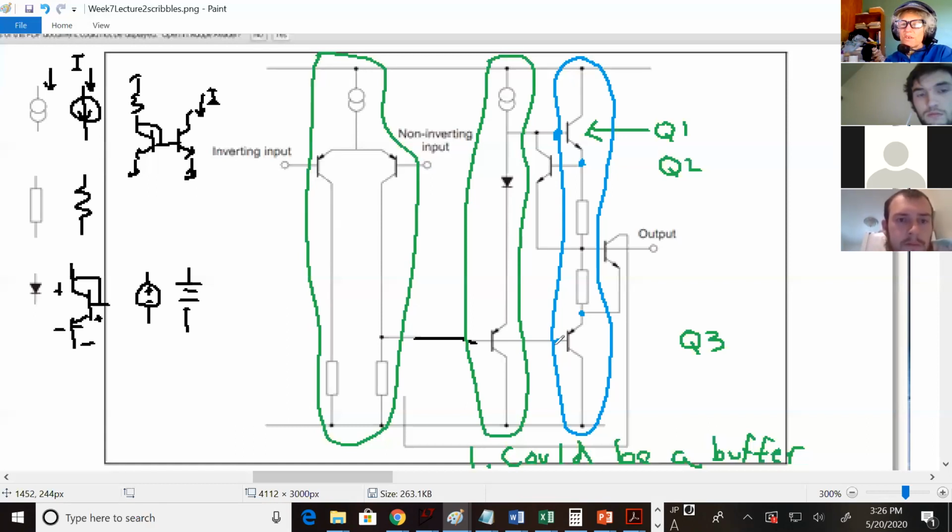If you go to this node, what is this voltage compared to this voltage? Another VBE on lower. So what's the net difference between the base of Q1 and the base of Q3? 2 VBE on. That's the voltage you have to set on the bases. What are you trying to avoid when you set it 2 VBE on apart?